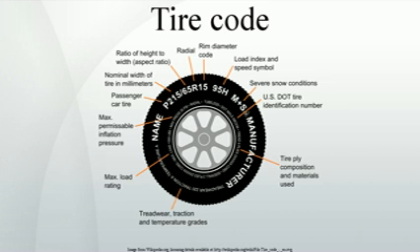The code has grown in complexity over the years, as is evident from the mix of metric and imperial units, and ad hoc extensions to lettering and numbering schemes. New automotive tires frequently have ratings for traction, treadwear, and temperature resistance, collectively known as the Uniform Tire Quality Grade, UTQG, ratings. Most tire sizes are given using the ISO metric sizing system. However, some pickup trucks and SUVs use the light truck numeric or light truck high flotation system.